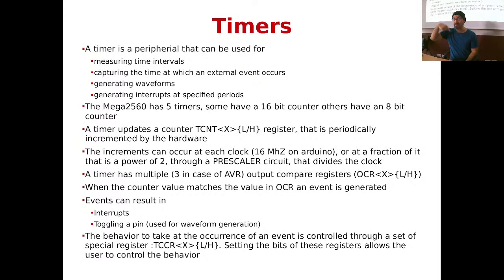In this way, with the same running timer, each time the timer goes on, you can generate up to 3 different events. You can say, ring the alarm when you reach 20, ring the alarm when you reach 100, and ring the alarm when you reach 800. Okay? That's how the AVR works. It's not me that made it this way. Why 3? I don't know why it was done like that, probably for silicon considerations on how many things you want to put on a chip.